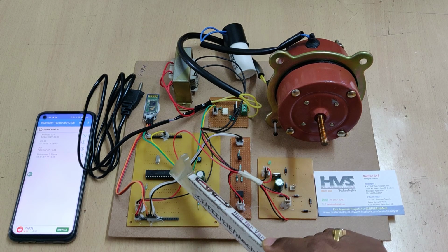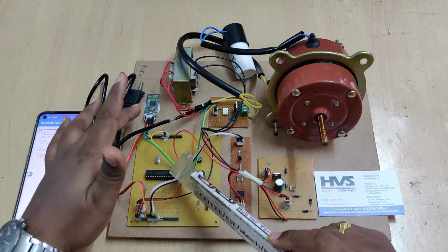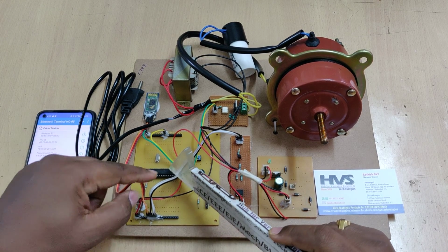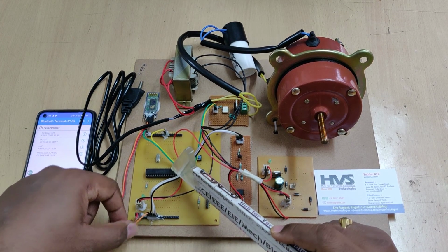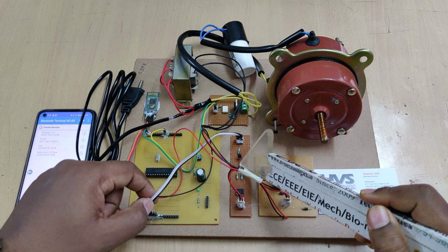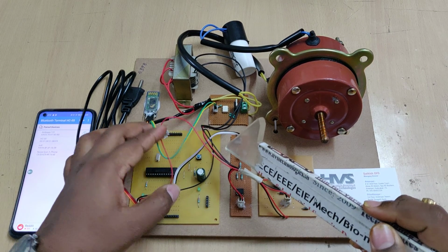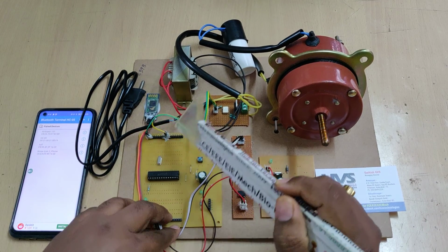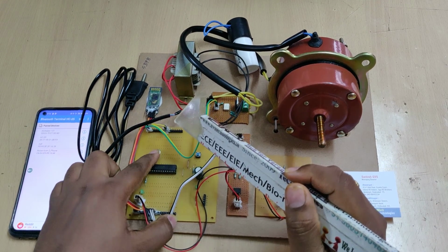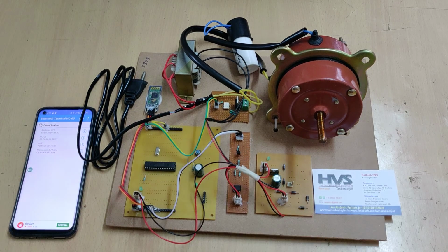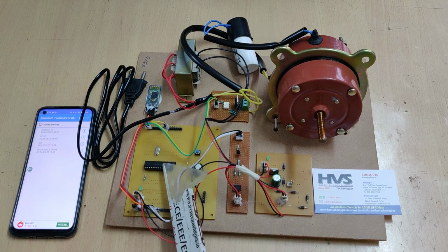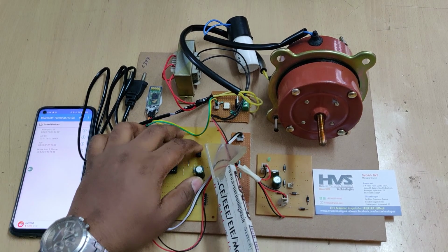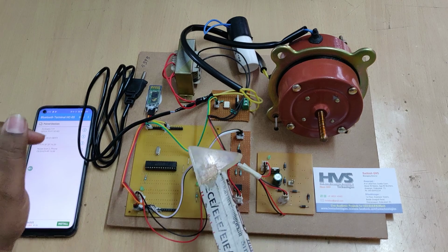Once it gets the power supply, it starts reading input from the HC05 Bluetooth module. We have interfaced it at pin numbers C6 and C7 of our microcontroller, the zero crossing detector at B0, and the triac at A5. On this motherboard we have 3 major components: the crystal oscillator to provide the clock pulse to the microcontroller, the microcontroller to read the input and control the outputs, and the reset switch to restart the microcontroller.